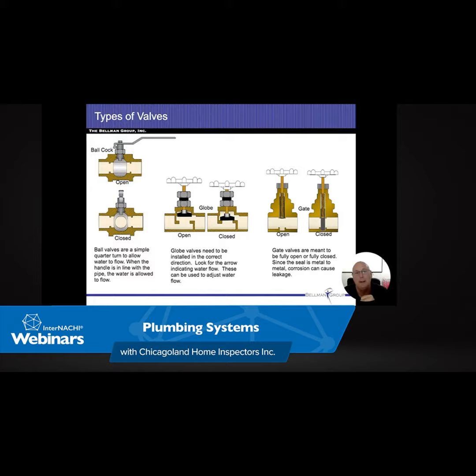This is another way to do it, and it's really not acceptable in our area, but from what I understand, it does work. I have seen it. I have tested it. I have not been able to make it siphon out. So what we're looking at here is a sink and an island. We put our trap. We start off at 1.5 inches.